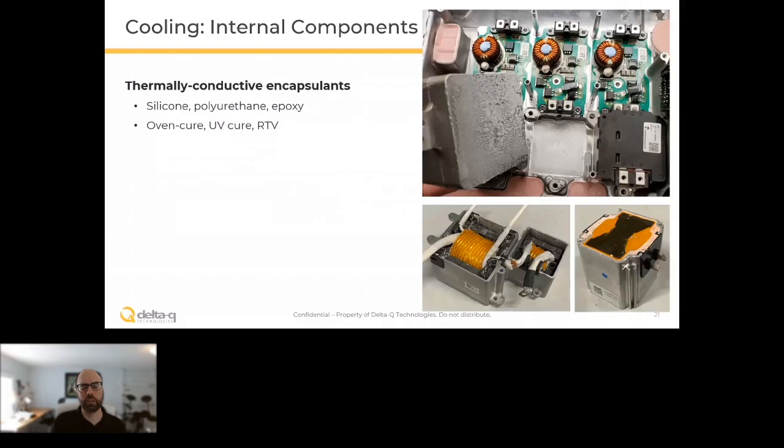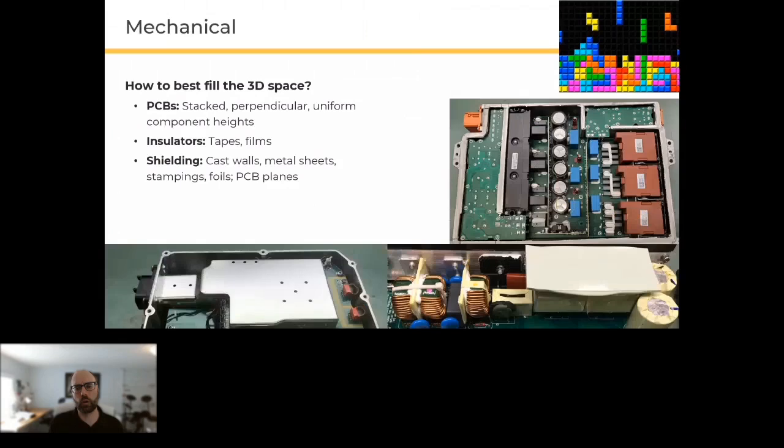That is a 10 kilowatt charger out of the Volkswagen ID3 and 4. And you've got an AC filter on the left, DC filter on top right, and a power board in between. And there's connections being made over a cast wall that's acting as a shield, and there's a board-to-board connection. On that power board, I see three vertical boards, three vertical daughter cards that are doing the control and the housekeeping power supplies. And you can't see this, but under that power board is another board stacked vertical, a metal core board that actually has the power devices on it.